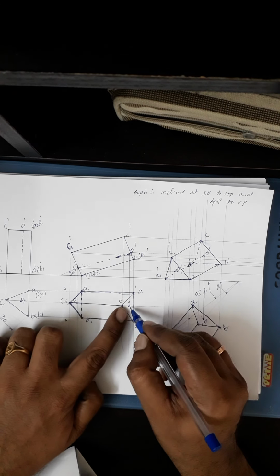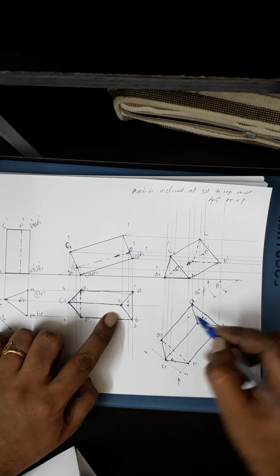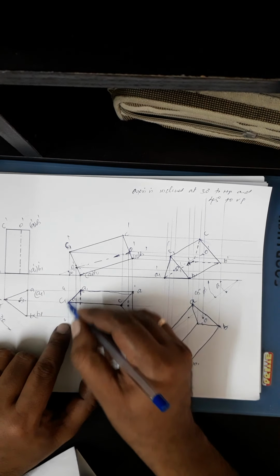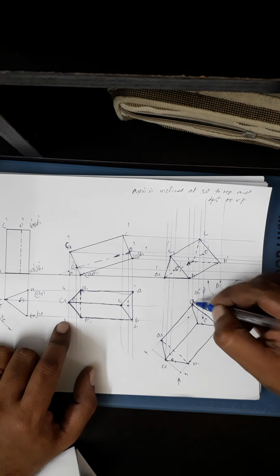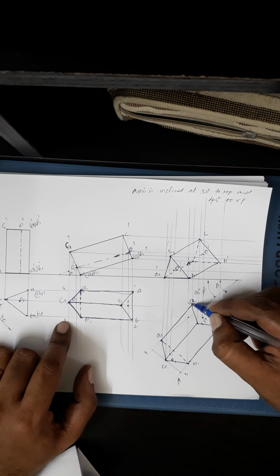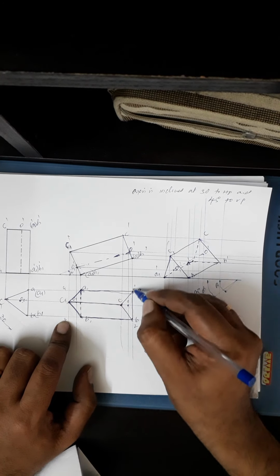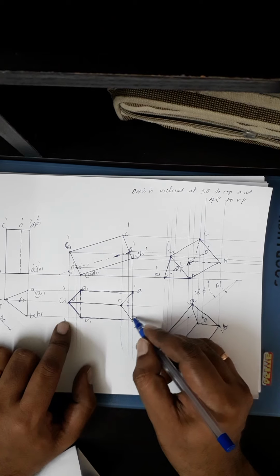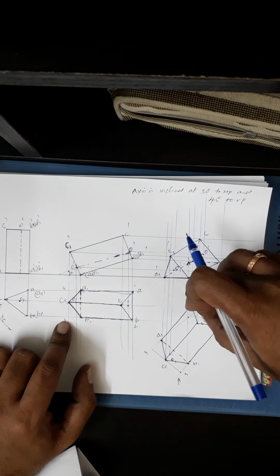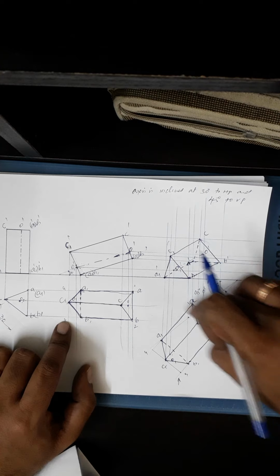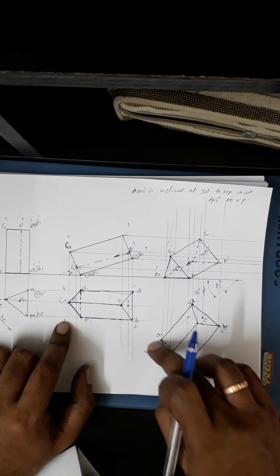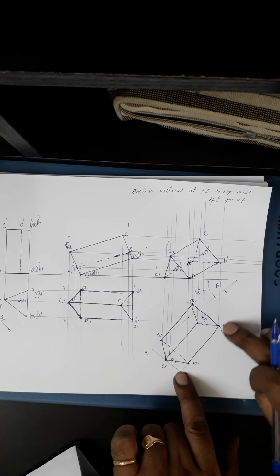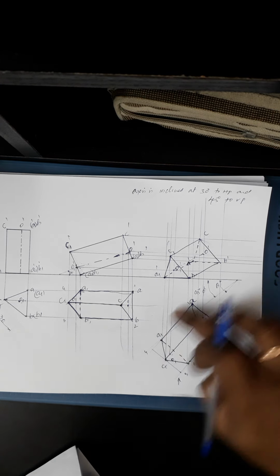Then for this axis line, from this end point I can take this length on this and go for drawing this 1, 2, 3, 4. I can inscribe this in a 1, 2, 3, 4 rectangle. So this will be 1 and this will be 2. I'll draw a line perpendicular to this axis line, because 1, 2 is perpendicular. Now these two are perpendicular. This length I can mark here, taking it on either side, and I will get the same length here. Then I can complete this 1, 2, 3, 4. Anyway, 2 to 3 I have, so I can take that length on the perpendicular line which is drawn, then complete this rectangle.